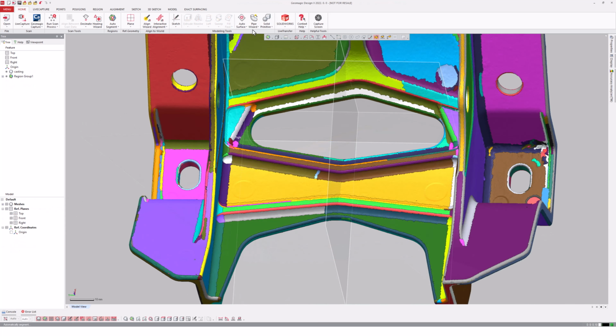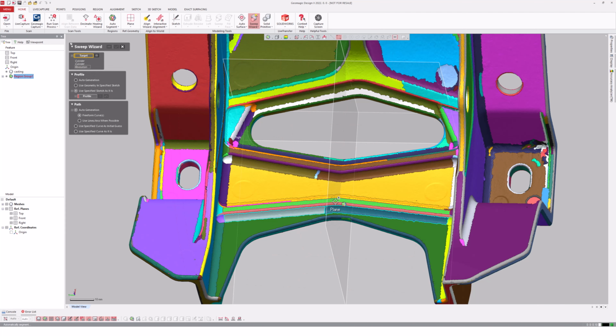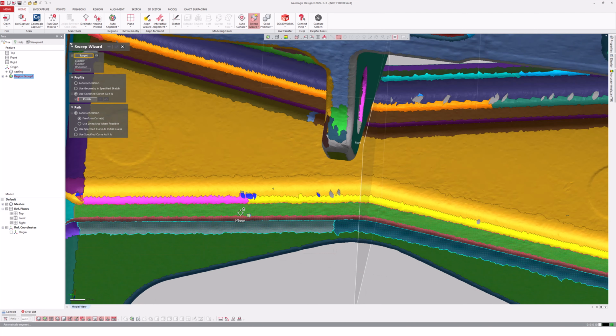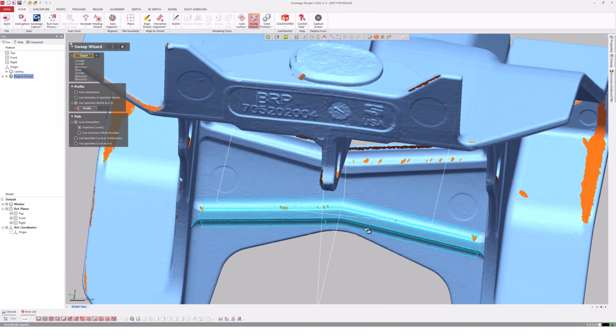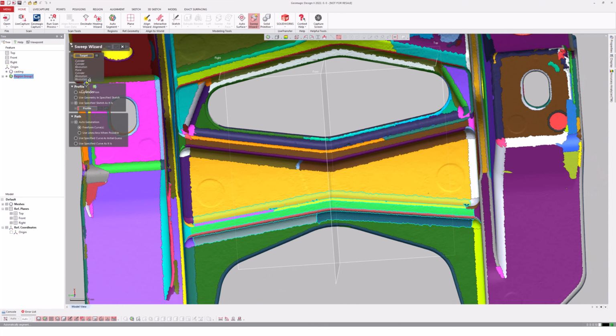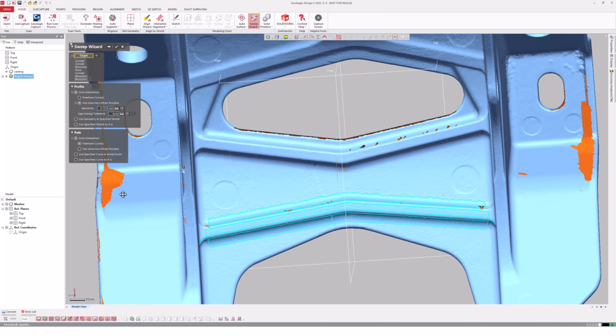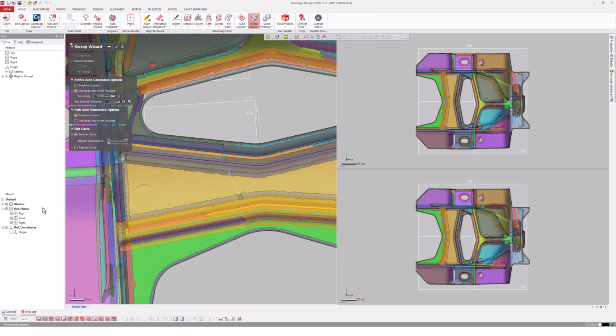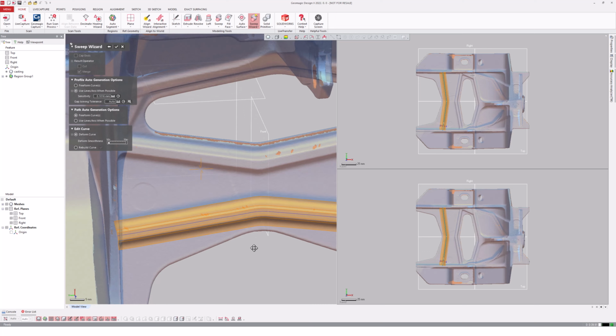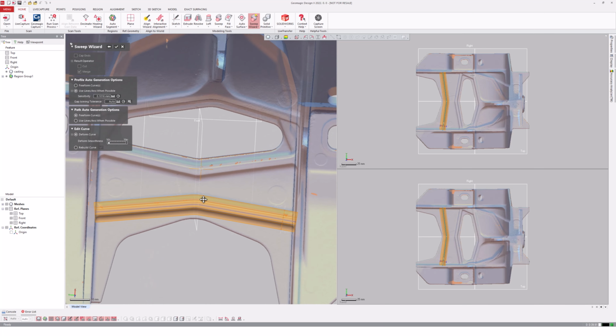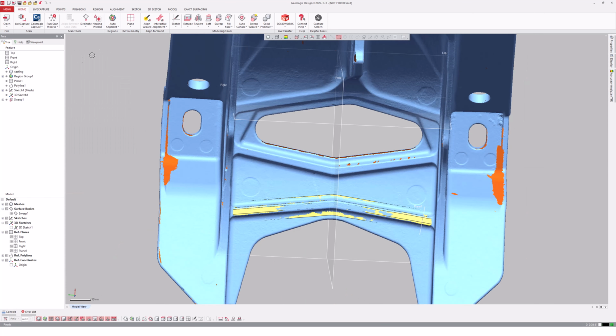The Sweep wizard can extract both a profile sketch and a sweep path from regions or a mesh selection, and the sketches can be either line art combinations or splines. An existing 2D or 3D sketch could be substituted for either. The second stage allows users to cap the ends, resulting in a solid sweep, which can be cut from or merged into existing bodies. There are also options to edit the extracted sketches.